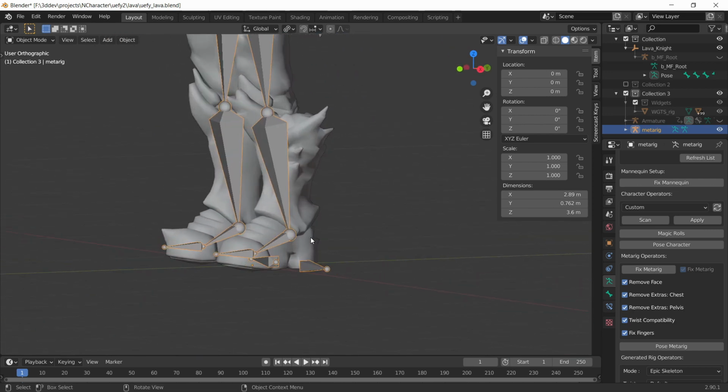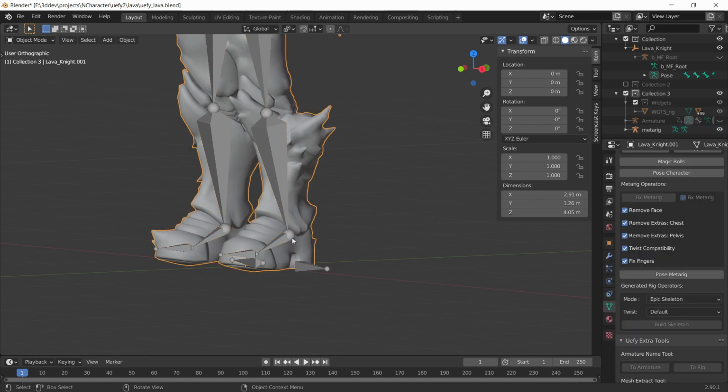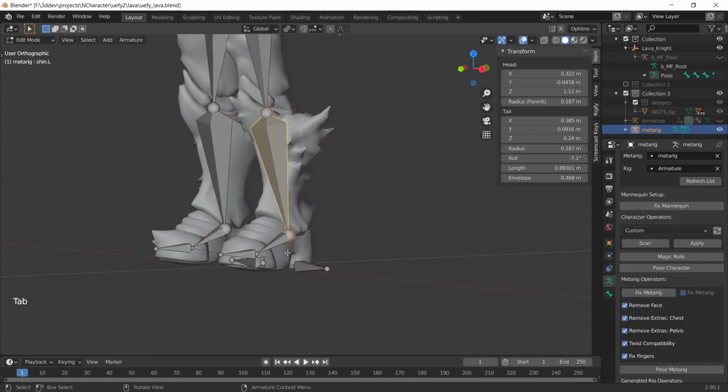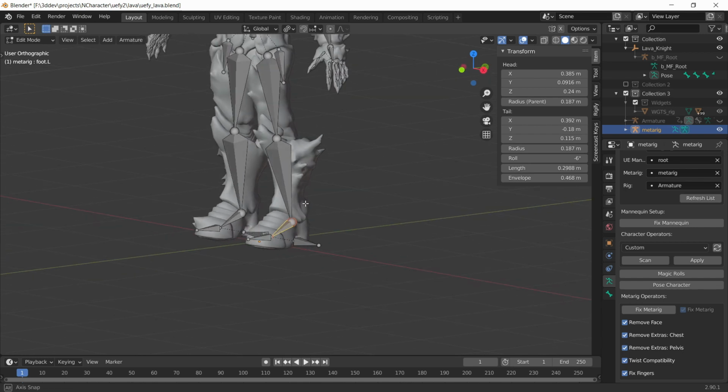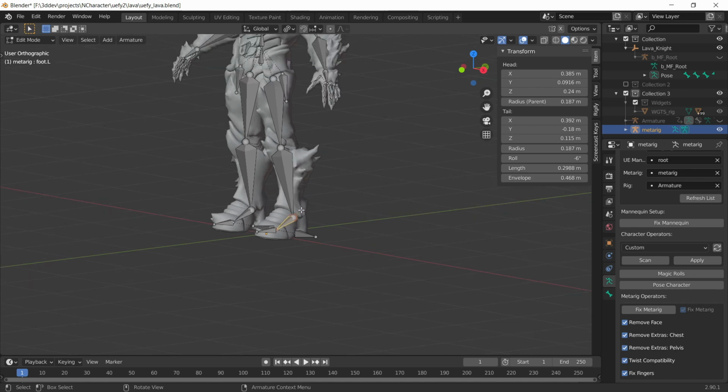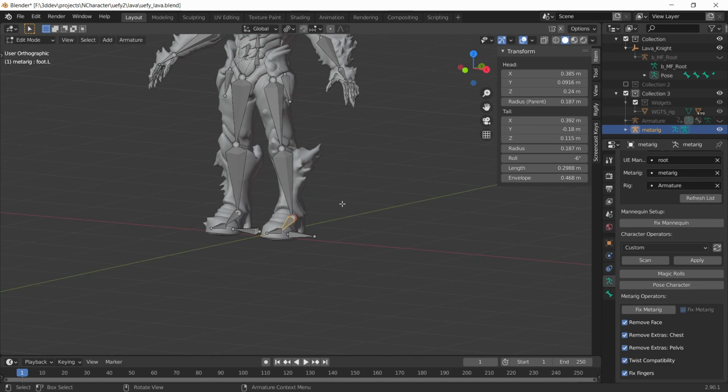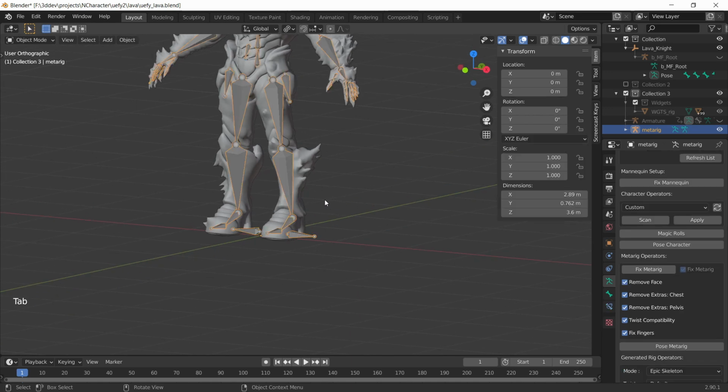But the problem here is that if you add a bone over here to the foot, you can see that this heel bone is kind of attached to this foot. So Rigify tends to get confused when you add attachments to this area of the rig. So we just tend to avoid it for this particular sample, for the limb or leg samples. But that's something we just have to accommodate Rigify for here.